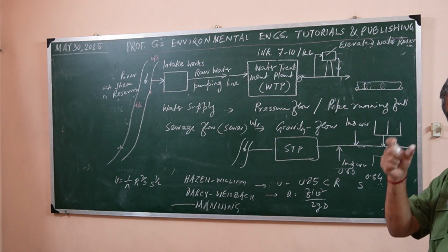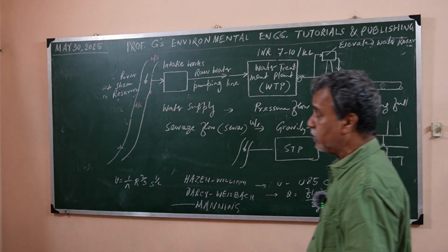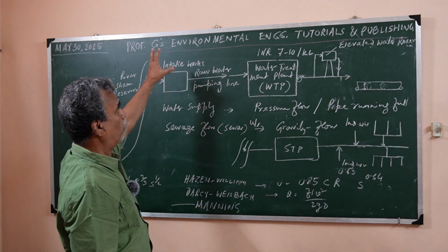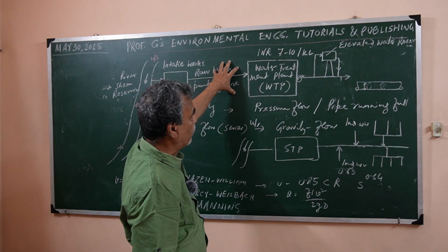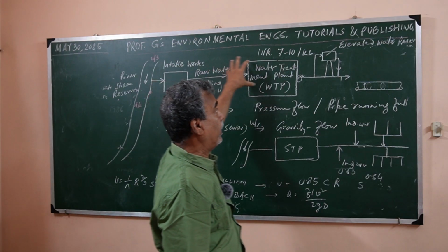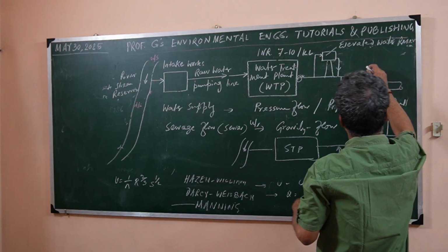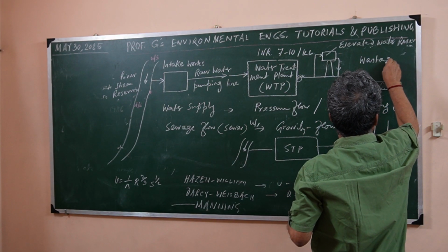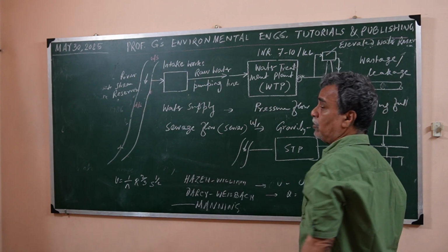That is, when you design the water distribution system or water supply system, remember that first the population which is to be served, then institutional and commercial needs are to be added also, and then an allowance is to be kept for the wastage or leakage.